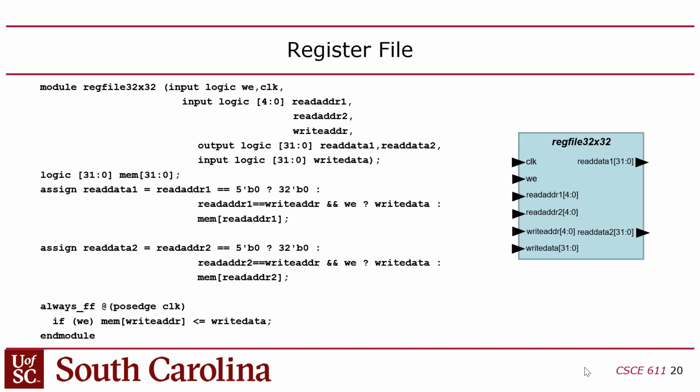You guys with me? Immediately after the instruction appears and the addresses go in, you get read data 1 and read data 2 out, which are the contents of the 2 source registers. Some instructions only have 1 source register, in which case you just ignore read data 2 because it's a don't care.